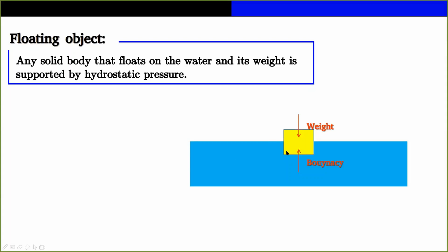Because this body, for example, is having an oscillation, something like harmonic motion in the vertical direction, at any moment it can have a different value of the acceleration and different value of the velocity. So we can have different added mass and different damping forces at any moment.